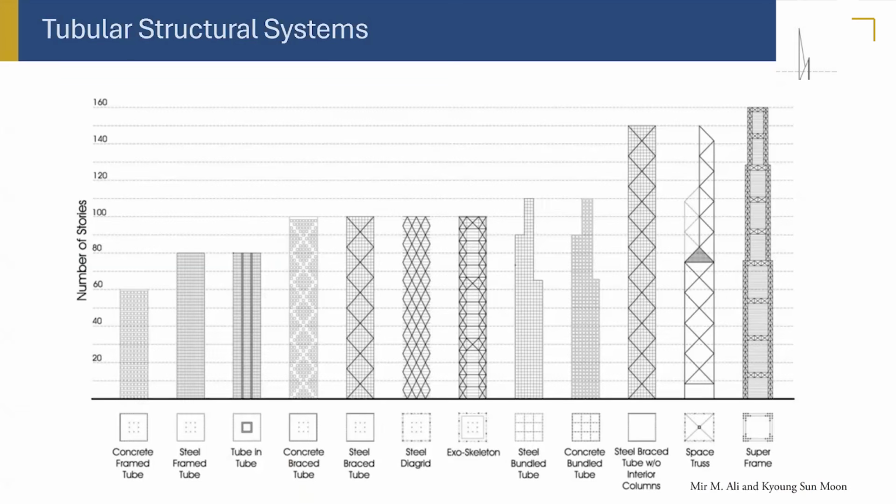This can go very tall, because you can keep making these super frames or mega frames bigger, and then keep making them. So inside the structure is actually nothing. You can think of this as one building with just 2 columns and these beams. Forget about inside. That's just filler. They're just hanging from these trusses.